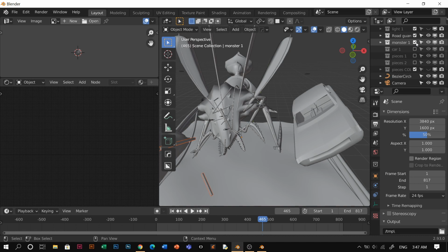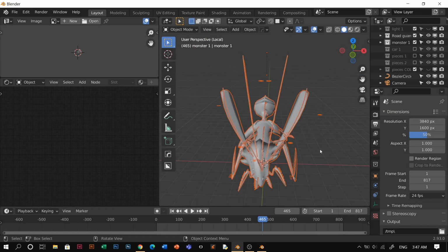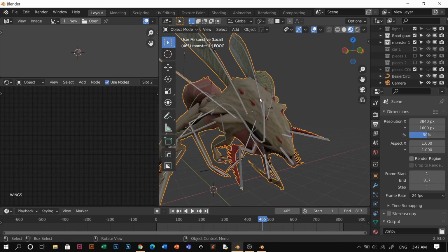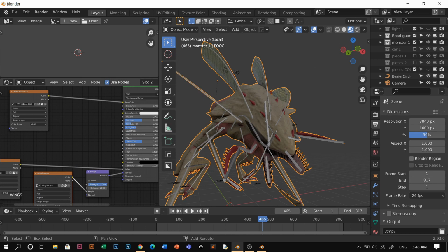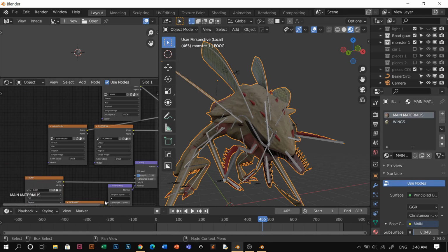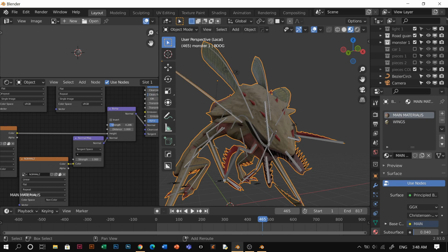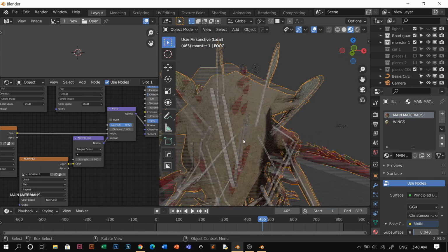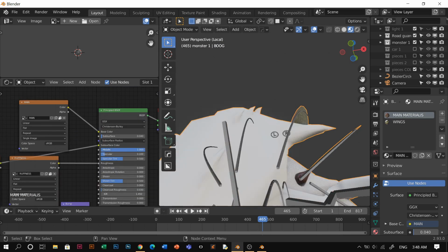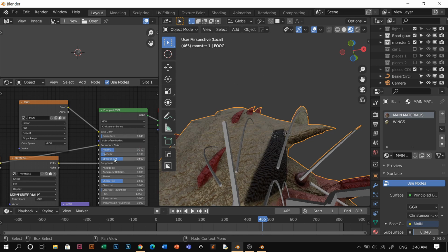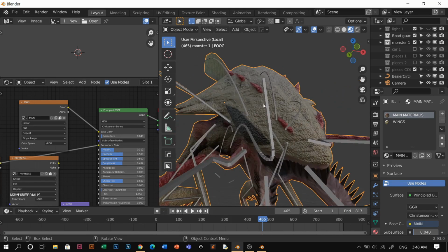And I'm gonna edit the monster. Go to select objects and let's have a look at the monster texture. Because it's not looking really scary, you might want to add something more. Main materials, add this bump higher so you could see the skin. And I'm gonna probably add metallic. No, maybe a bit, yeah. And turn down the roughness there. Specular to 0.5. And I like to make it look wet.